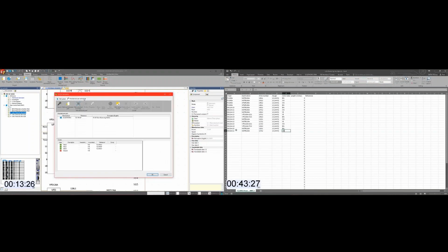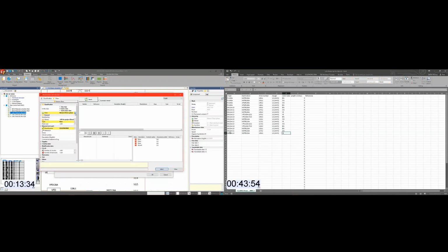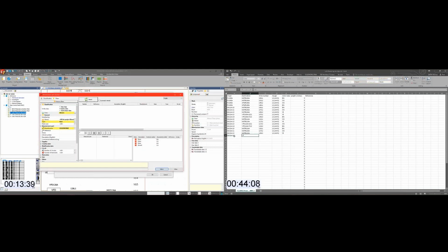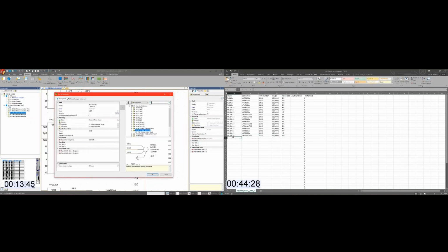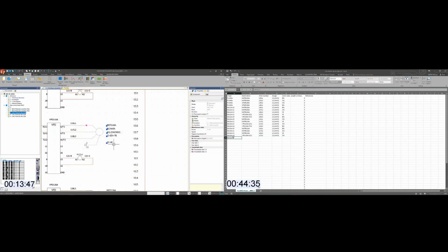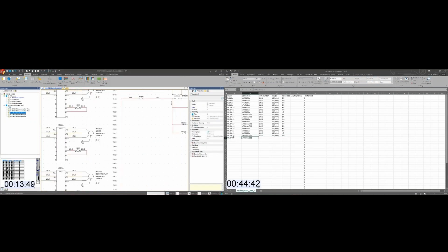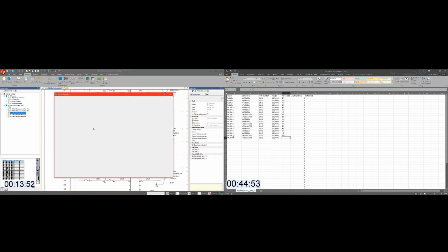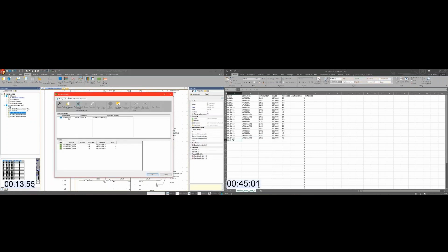So I have documentation created, etc. All I have to do in SOLIDWORKS Electrical is simply come over and make the change in one place. So I've removed that part number. The symbol isn't related to that part number. So as I assign a new part number, in this case, a 25 horsepower motor, all those properties come over and will populate and update into the existing symbol. So that part number has been updated to reflect that. I'm also going to change the part number inside of this circuit breaker.